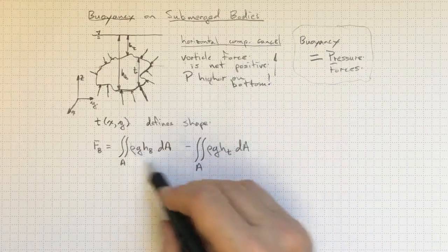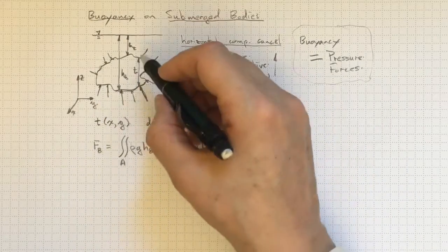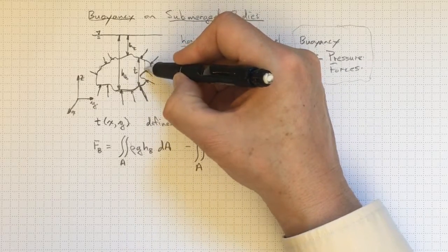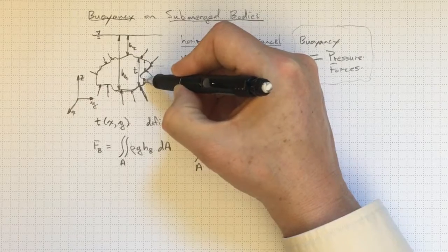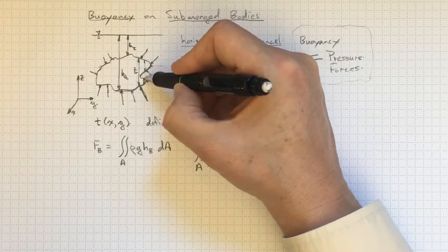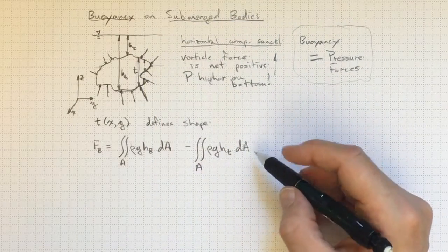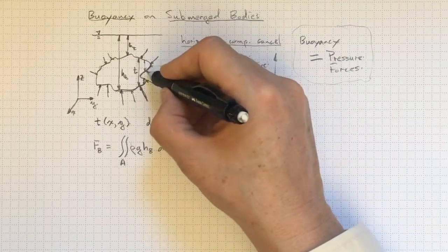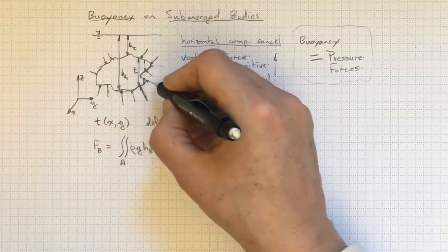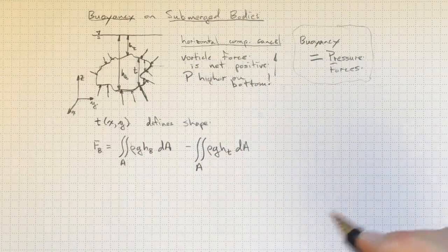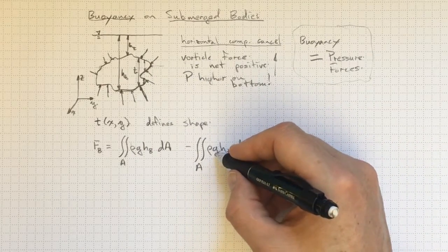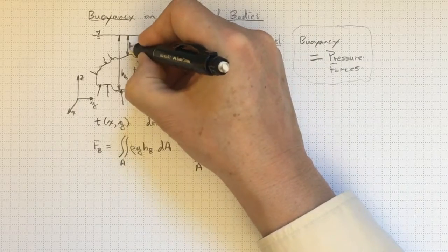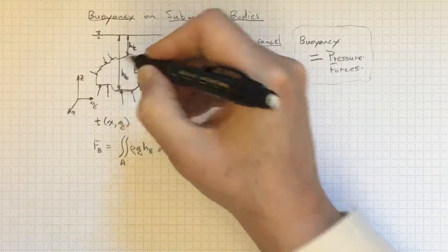So if we do our accounting carefully and make sure that we get all of the area and only the appropriate thicknesses associated with that area, so we'll have two separate little chunks over here where we've got this concave bit on the side, then our integral will work out. We'll be calculating all the pressure forces all the way around, and we can combine that by noting that the thickness is the difference between the height at the top and the height at the bottom.